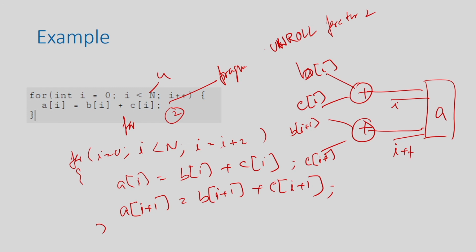So, one important point to be noted here is that with this unrolling, the access of the array is getting increased. You can see here that earlier, in every clock I am going to access one time A, one time B, one time C, right. Now if A, B and C are mapped to, say, block RAM, and I am doing the factor of 2, I can see that in every iteration I am accessing 2 values of A, 2 values of B, 2 values of C, right. So, if that particular block RAM is single port, then this will create a bottleneck, because you cannot access 2. So, this benefit you will not get, right. So, you have to still do it in sequence.